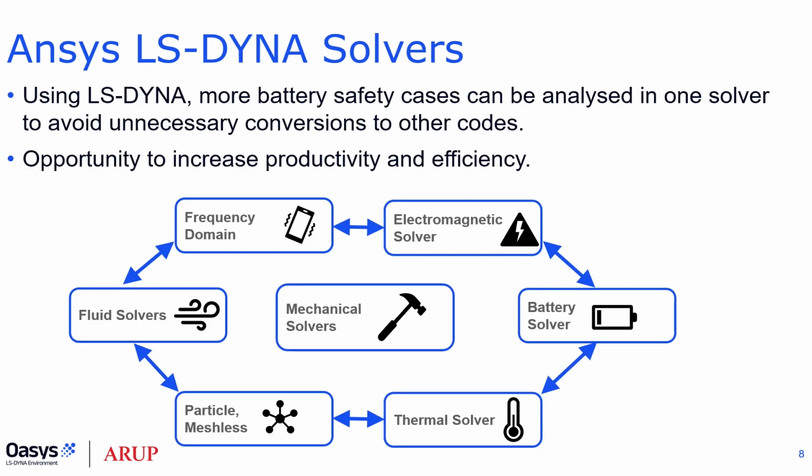In fact, many of these battery safety load cases can be analysed using LS-DYNA. LS-DYNA is a multi-physics code, and it's got a number of coupled solvers that are designed to work together. And in addition to the mechanical solver, there are thermal solver, frequency domain solvers, fluid solvers, and electromagnetic and battery solvers that will all work together. So if we have a battery model that's already been made for crash analysis, there's a good chance that we can use it for vibration and thermal analysis without many difficult changes. And this should give us a boost in efficiency because we only have to use one model in one format.